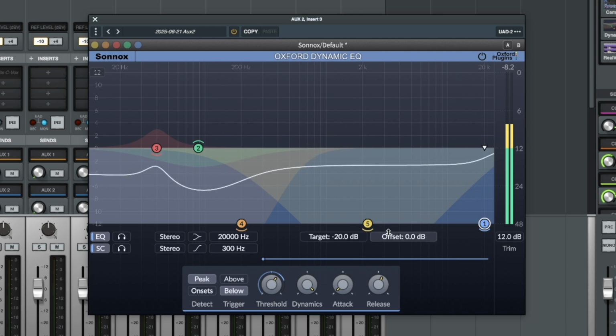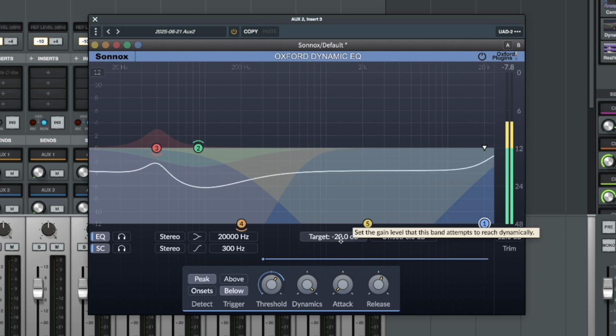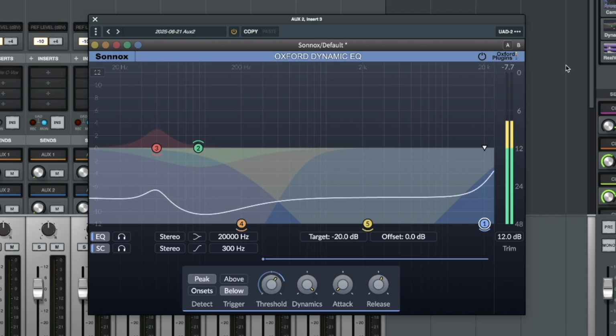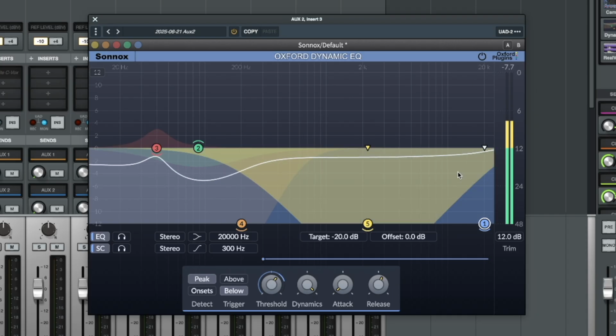So it's cutting it down by -20 dBs, and the filter frequency is at 20 kilohertz. So it's kind of a way of simulating a noise gate. Normally you'd have a separate noise gate plugin. As you can see in here, I'm quite limited on the number of plugins I can put in the chain. So that's how I'm doing the noise gate in here.